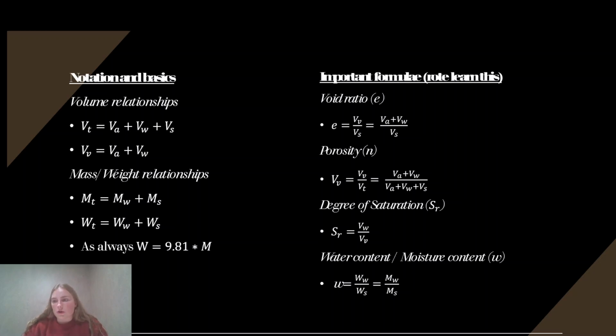And also in this course, it's important to note that soil particles are taken as incompressible. So soil particles cannot change in volume, they're a constant. Water is also taken as incompressible, so it's a constant. So the only thing that can change when you compact or densify your soil is the volume of air in your voids. The next one is porosity. Porosity is a measure of how porous soil is. An important thing to note is porosity is not the same as permeability, so please don't mistake porosity for permeability.